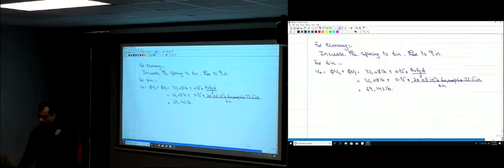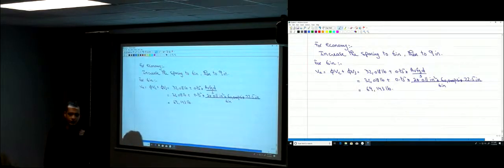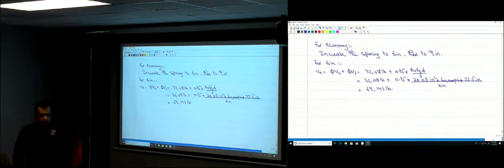Okay? So at what point is the shear equal to that value? How can you find that point? From the equation. Which equation? Our line equation we solved earlier. So V at the distance x is 100.8 K minus 12x.